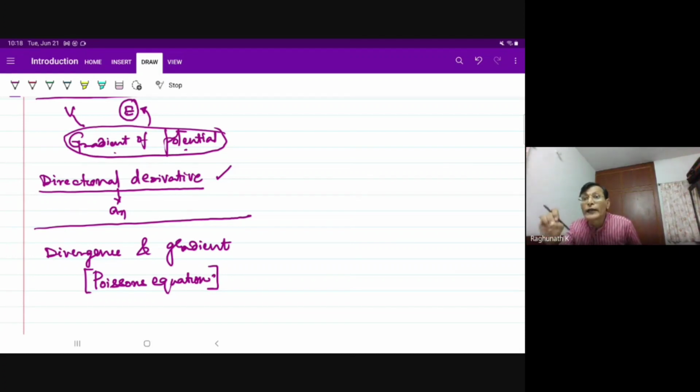If you want to really understand the electrical behavior of a PN junction, or iso junction, PP plus junction, NN plus junction, P plus N junction, PN plus junction, whatever, the first thing you have to use in a given junction area is Poisson's equation. Using Poisson's equation, we determine the junction field at each and every point in the PN junction.